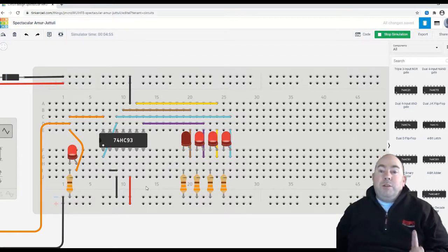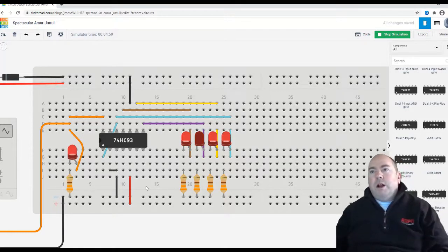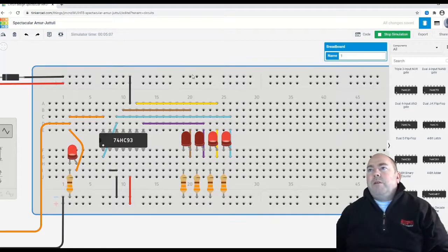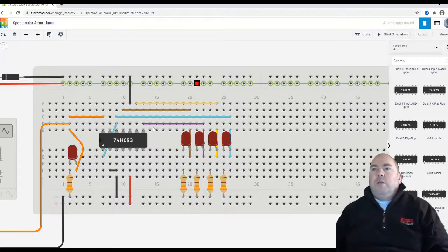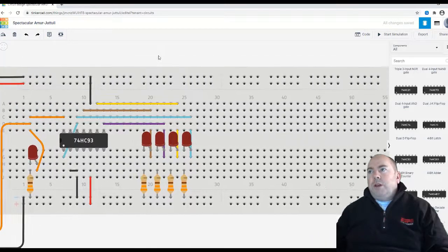And we are actually going to do that in the next little chunk of the lab here in part E, where it shows us how to make a count-to-60 counter using 2 of these chips. So we're going to do that now. We're basically going to duplicate this and then do a little bit of logic that's going to do some resetting for us as well. So let's duplicate this setup here right now.